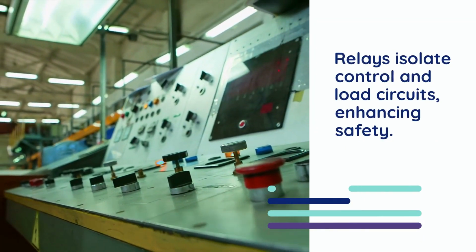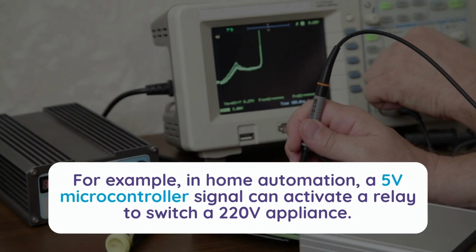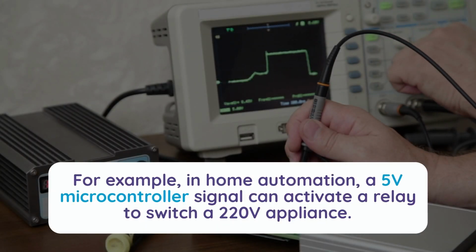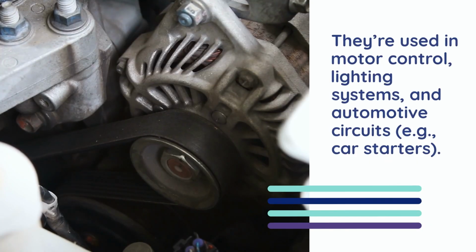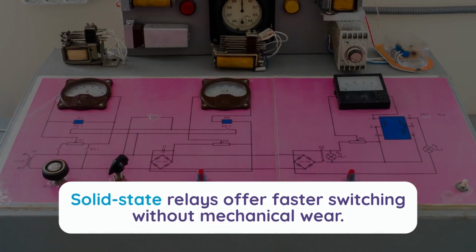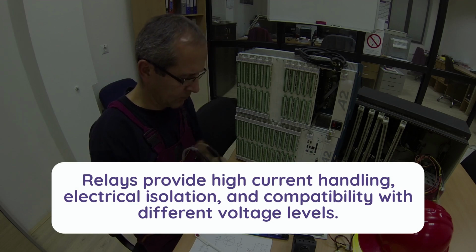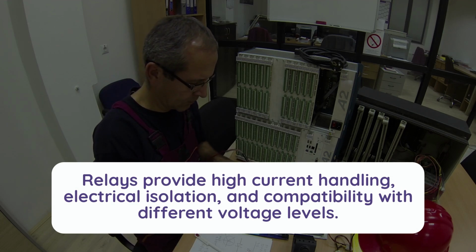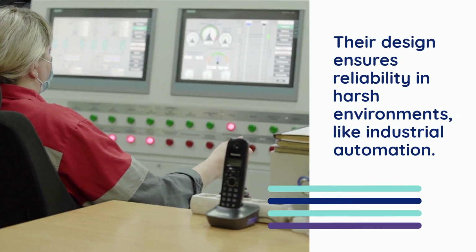Relays isolate control and load circuits, enhancing safety. For example, in home automation, a 5 volts microcontroller signal can activate a relay to switch a 220 volts appliance. They're used in motor control, lighting systems, and automotive circuits, e.g., car starters. Solid-state relays offer faster switching without mechanical wear. Relays provide high current handling, electrical isolation, and compatibility with different voltage levels. Their design ensures reliability in harsh environments, like industrial automation.